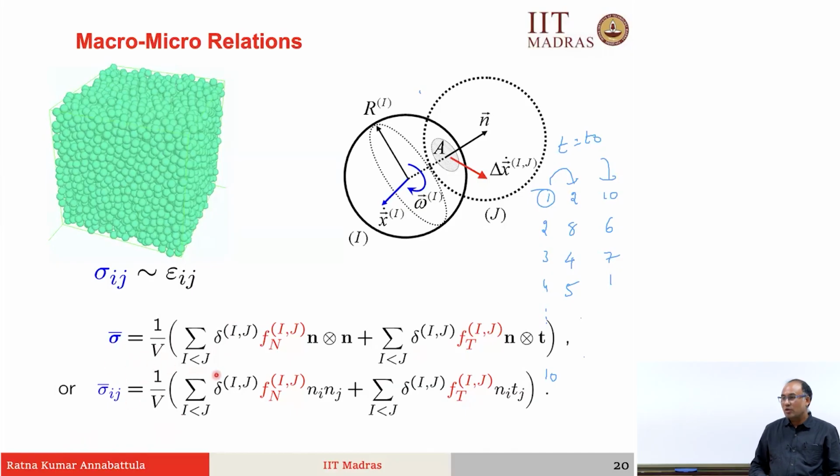This is one way of computing macroscopic stress. There is another way. You are applying force, the displacement. So, this wall through which you are applying the displacement will experience some reaction force, isn't it? Yes or no? So, that reaction force divided by the area is also a macroscopic stress, isn't it? If you are interested in that stress quantity.